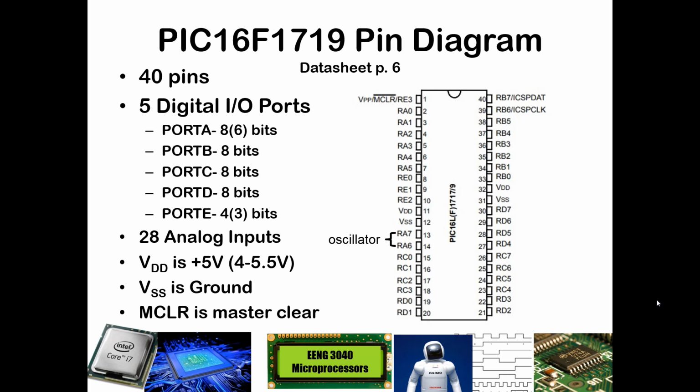One thing that is important to note is how pins are numbered. So you see the notch that we have right here at the top of the PIC, and then the pins are numbered starting at 1 just to the left of the notch all the way to N/2 on the left side. So in this case, N is 40 pins, so we've got 1 through 20 on the left side, and then you take a U-turn, and you've got pins 21 through 40 on the right-hand side.